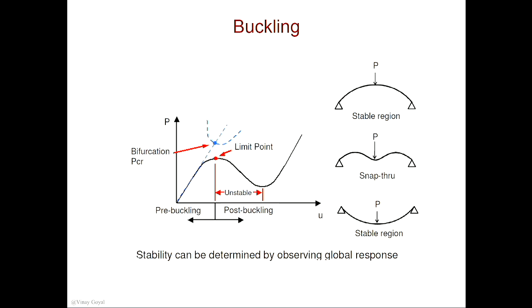Well, that's clearly unstable. At the same time, when it encounters this load deflection curve, this portion, I can increase the load and that will be fairly stable at that point. If I were on deflection control, so I'm applying the deflections myself and tracking the load instead, then for every deflection as I increase it, I can calculate a load. However, you can see the load is decreasing. So as I'm increasing the deflection, less load is needed to support that structure, right?